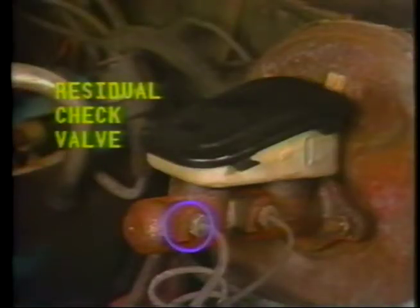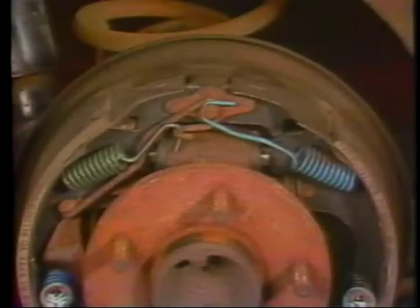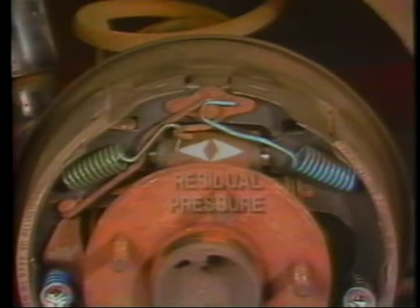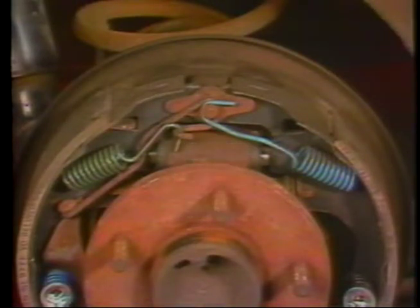The residual check valve in the master cylinder maintains a slight residual pressure of approximately 6 to 20 psi in the line when the pedal is released. It's only used on drum brakes. Its purpose is to take up the slack in the brake linkages and also keep the wheel cylinder seals tight against the wheel cylinder housing, thus preventing fluid from leaking out and air from leaking in.